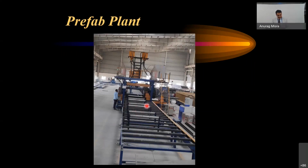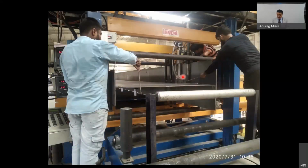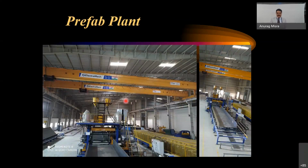And once it moves, it is something like this, moving on these rollers you can see here, and then it comes to the welding arm. So these two people, total three people are required. They are not doing anything there. They are just removing the scale which is coming out after the welding. Right. So this is the robotic arm. There is one inside. So welding is going on both the sides of the I-girder simultaneously, and this beam is moving in a way that continuous welding is achieved on this web and flange. So that is how it is advantageous and faster.